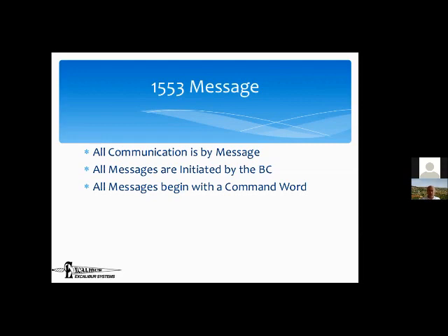Some data will go to the RT, some will come from the RT, but every single message is initiated by the bus controller. And the first word of every message is the command word, and the command word, therefore, is written by the bus controller. So every message on the bus will start with a command word, which is transmitted by the bus controller.